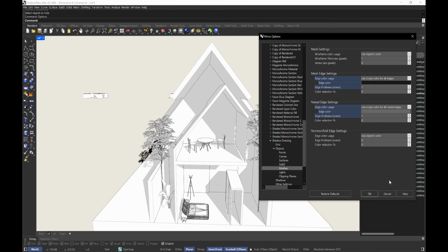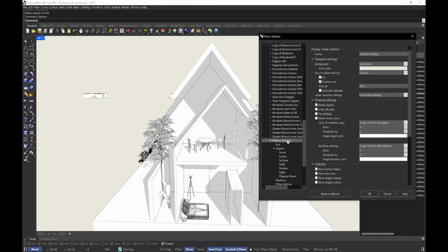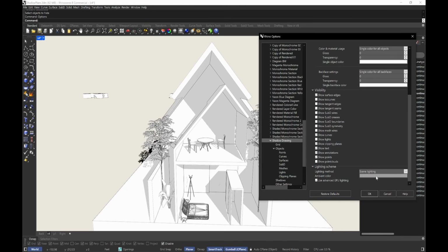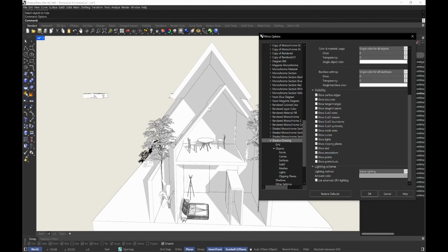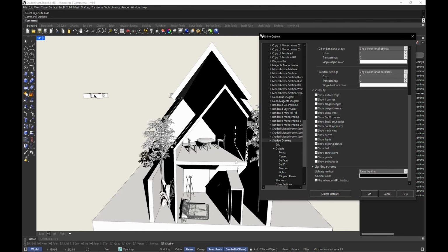And let me just go back for the lighting, because for that more simple gable example I showed you, I made the ambience black, right? So if I click on the main setting here and I scroll down, I made the scene lighting black, right? So if I go here, I made this completely black, and just give it time to update. But you see now how the shadows are very strong. Everything's very strong here, okay?